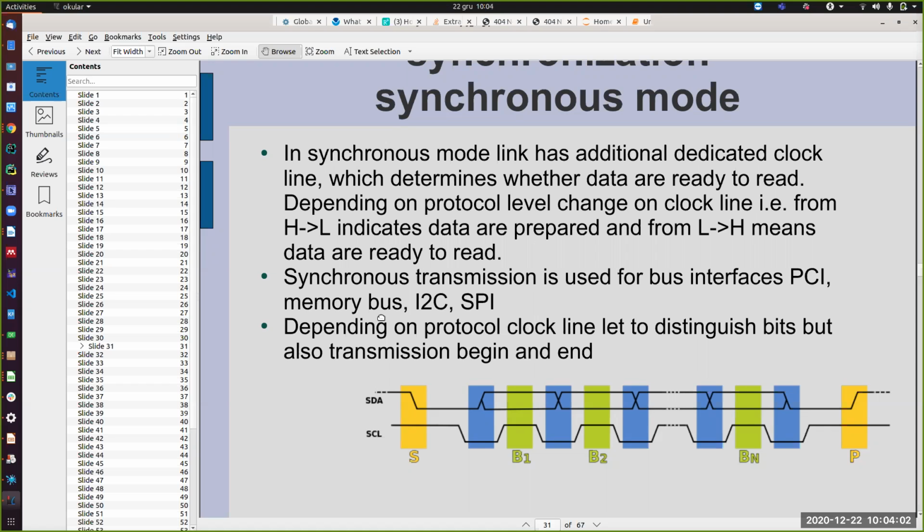Sometimes when you look at the main board or some high frequency printed circuit boards, you can see that some paths have meanders because we have to align the path length. So this element has to be considered when you have so high frequencies.